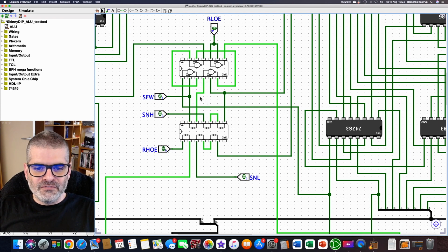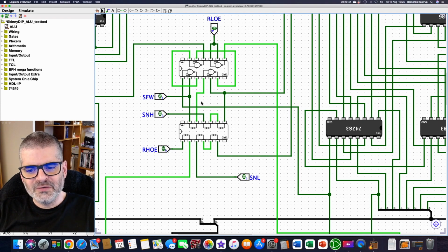Or even if you put a resistor to limit the current through the LED, but you use that same pin to drive a logic value to another chip, keep it running for a while, and then have a look at the voltage levels, and you will see that they will be oscillating. They will introduce funny errors to the circuit, which will be a hell of a problem to troubleshoot, because they will be intermittent problems. They will happen now and then. And you will not know any of this, you see.